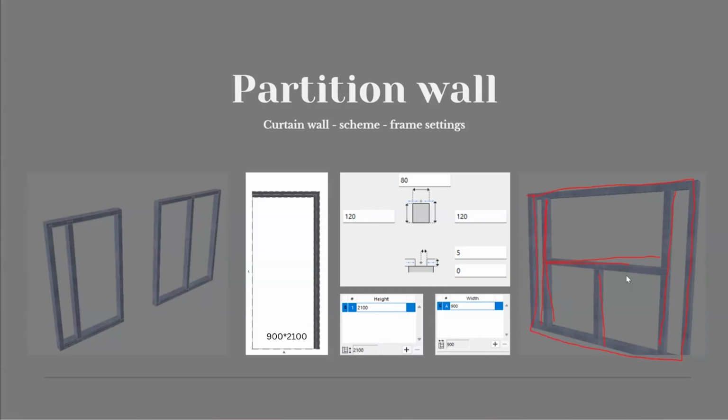But by any chance, if you want to add something extra, let's say a diagonal frame, that becomes another typology altogether. So when you work with ARCHICAD, you can create n number of types with respect to the frames and also panels. But right now, what we need is just one type of frame altogether. And that one type of frame is assigned to the frame here and the frame here as well, and that will be used. So I was talking about the boundary frame, mullions, and transoms.